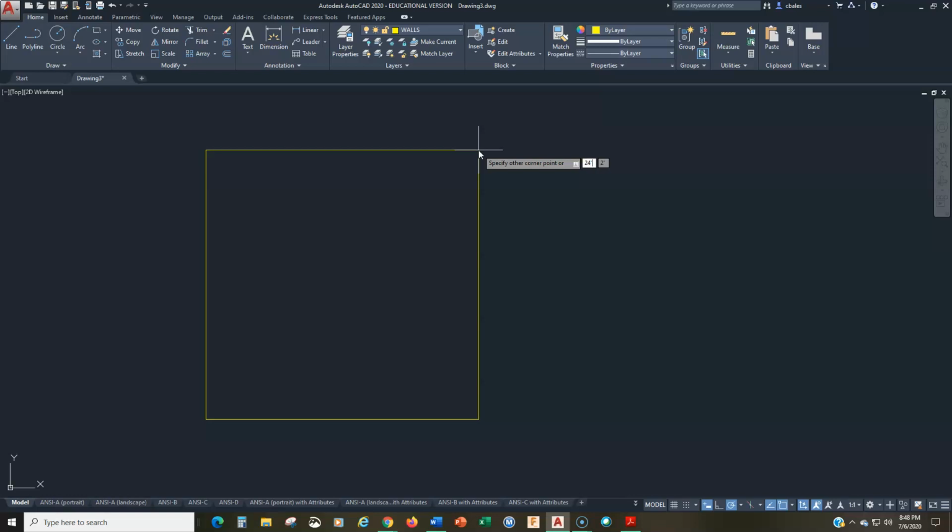Okay, and then I'm going to hit the tab to go to the height, or the y distance here, the vertical distance, and that on the architectural drawing is 30 feet. So where it's highlighted blue, the 2 apostrophe right there, I'm going to type in 30 feet. And now I have everything entered. I'm going to hit enter.